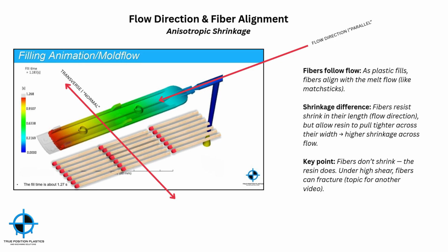A huge difference. For example, take a 30% glass-filled nylon. It might shrink as little as, say, 0.3% in the flow direction, but then as much as 1.0% in the cross-flow direction. That's more than triple. Exactly. And we see this consistently in material data sheets. Take a 20% glass-filled PBT: molding shrinkage parallel to flow is typically around 0.40%, but shrinkage normal to flow can be 1.20%. Again, 3 times higher. It's a fundamental behavior of these materials.